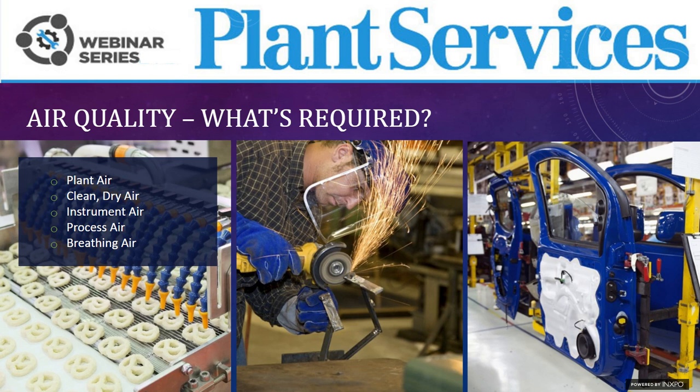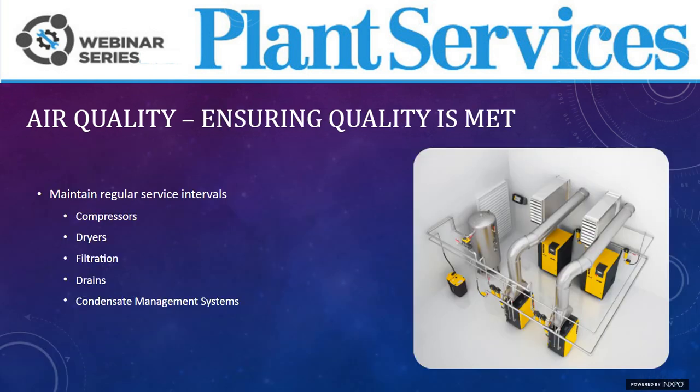Particulate must be less than 40 microns, and that oil concentration must be less than 1 part per million. So, the ISA standard also notes that air quality must meet the requirements of the user. So the burden then ends up falling on the user to understand and be aware of the requirements needed for their particular application. And so with that being said, let's look at what we can do.